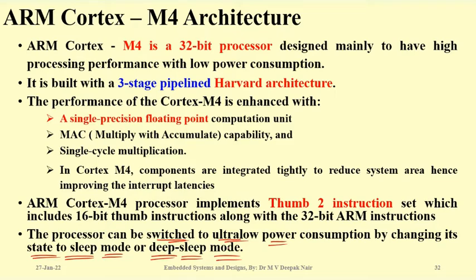For example, when your computer is not working, automatically it goes to hibernating mode. The monitor gets off, the computer goes to sleep mode, so that it can save power. If you are not using your computer for more than 5 or 10 minutes, it goes to sleep mode. Similarly, you can program your system using these kinds of microcontrollers, so that you can push them into deep sleep mode. Not only sleep mode, but deep sleep mode, which further reduces the power consumption.